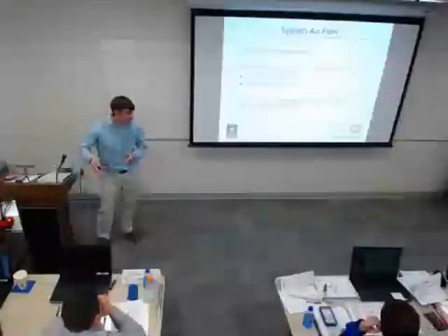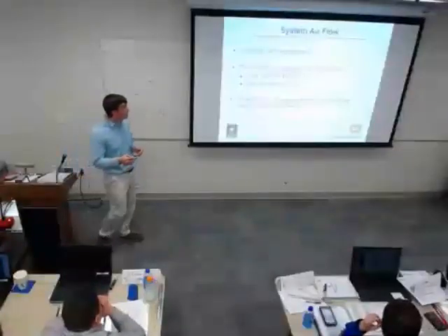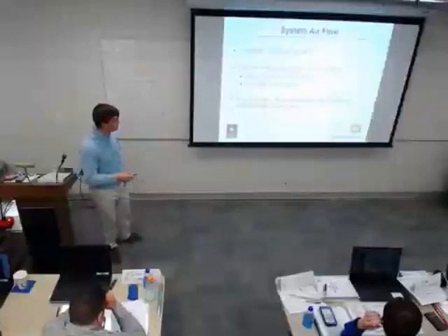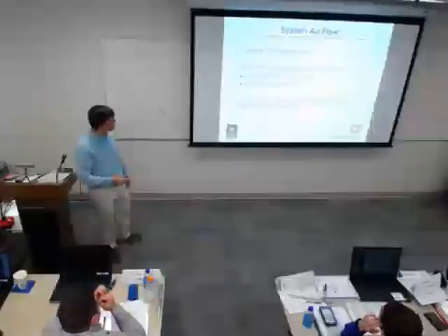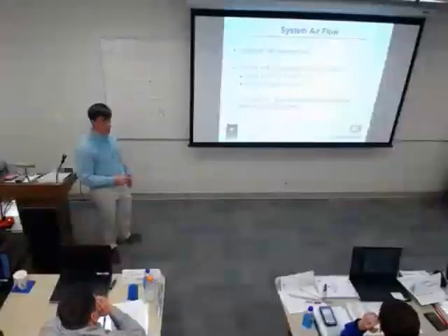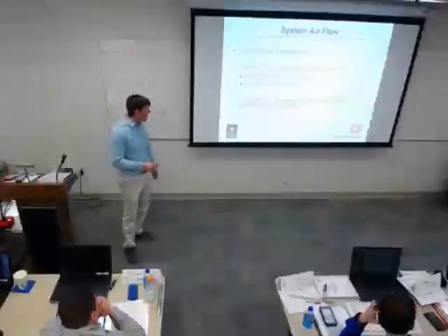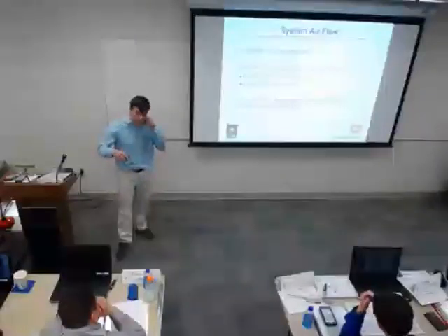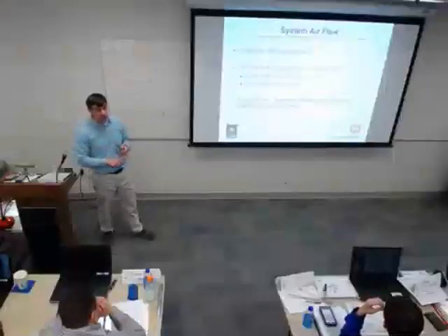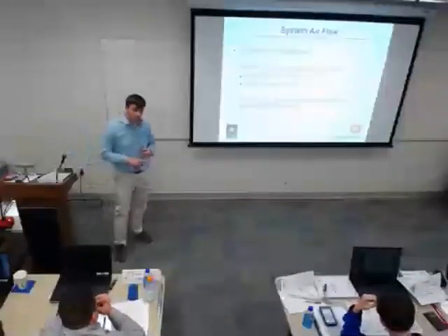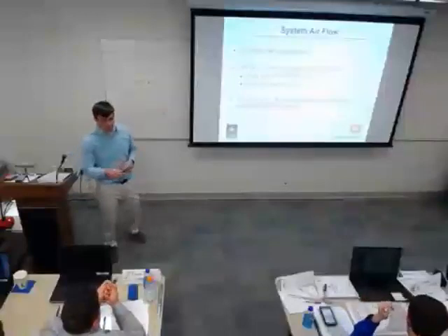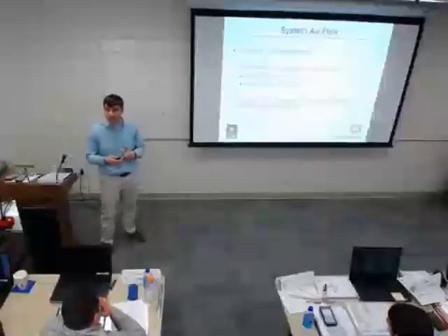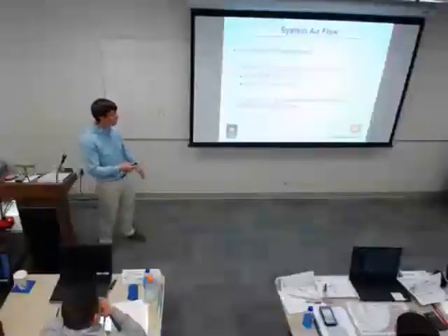All right, shifting gears out of system effect to system airflow. We talked about measuring pressure earlier, and now we're getting into airflow. We're talking about cubic feet per minute again, versus liters per second for SI. And I want my actual airflow after accounting for density. Remember we talked about standard conditions, which are 70 degrees and sea level. I think you showed a slide earlier: whether it's down to 40 degrees or up to 100 degrees, I don't care temperature-wise, but at about 2,000 feet of elevation I've got to make some sort of correction.